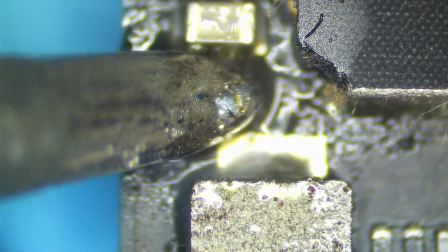Definitely in a tight area. Main thing is I've got to increase our temperature up here. I'm going to go full on 840 for this. I've got to get those pieces of the capacitor out of here. There's pieces of that capacitor that really need to go. And it would actually help if I set my iron to 840 instead of just leaving it there on the prompt. There we go. Look at that. Beautiful. There's still some pieces there, so I'm just going to work these out with my iron, just like that. There shouldn't be anything left there, but we're going to wick the pads. Beautiful. So those pads are wicked. Let's clean this up with a little alcohol.